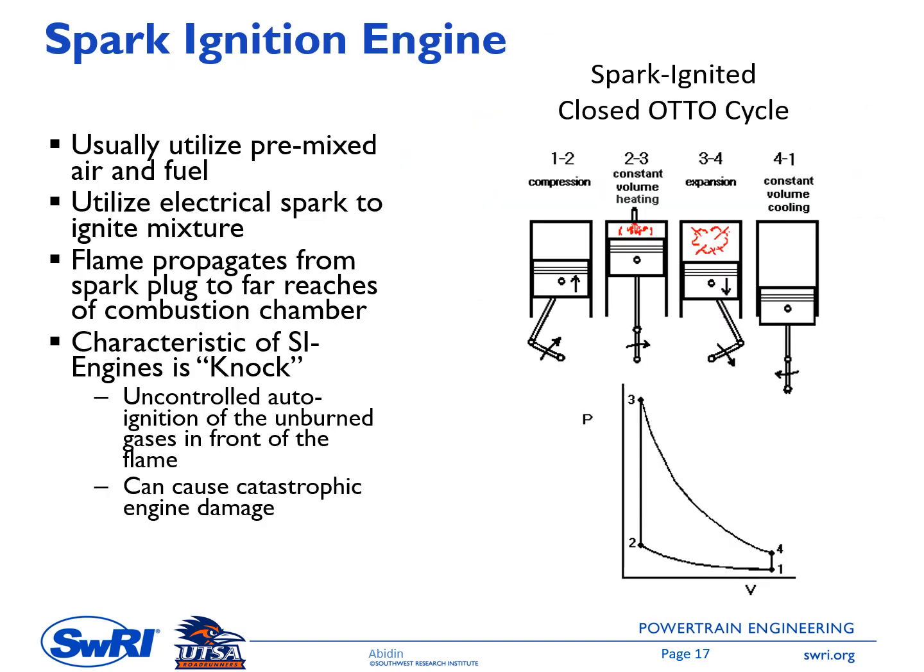Okay, let's go back again to the reciprocating internal combustion engine, and in this slide we will talk in more detail about the spark ignition engine. In a spark ignition engine, we can have a premixed mixture, so a mixture of air and fuel entering the engine, or we might have only fresh air entering the engine, and then the fuel is injected directly into the cylinder during the intake stroke or during the early part of the compression stroke.